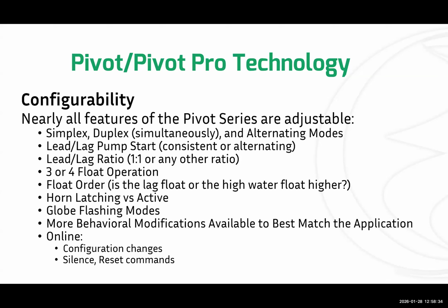You don't want it to just come on, pump the basin down, and mask any problem. Like maybe the first pump has failed and that second pump has to kick on in order to cover for it. Well, you want to know that. And so if you have a 3 float operation where lag and alarm operations are tied together, you're going to know it. If the lag float comes on, it's also going to sound the alarm at the same time, and that's what you want. The one exception to that is if you have a stormwater application.